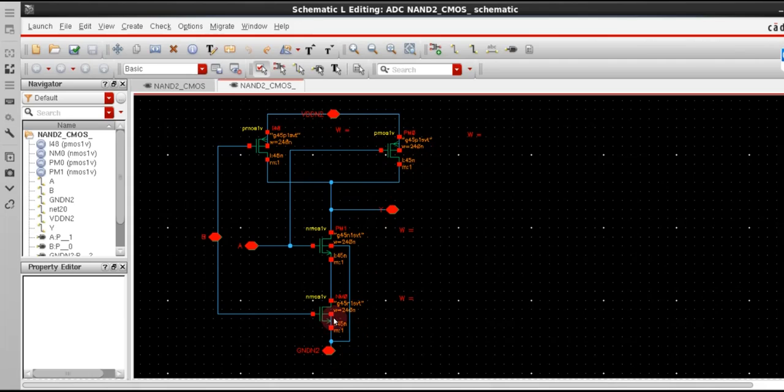Now if you go through my VLSI lectures, you will find how the sizing has been done here. Normally for a unit inverter, the minimum width for a 45 nanometer device is 120 nanometer. A unit inverter will have NMOS of 120 nanometer and PMOS of 240 nanometer, because PMOS is slower than the NMOS because of the lesser mobility of the holes. So generally we keep the width of the PMOS twice that of the NMOS, so that the rise time and fall time are the same.